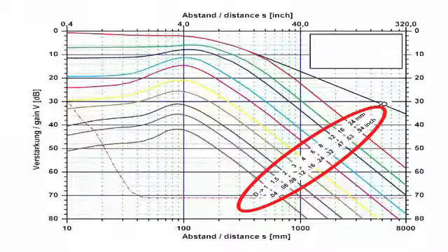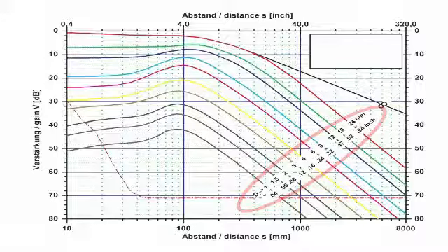In practice, different types of reflectors can be used as reference reflectors. When testing using normal beam and TR probes, a flat back wall is often used, which is struck perpendicularly by the sound wave. This can either be the back wall of the workpiece itself or the back wall of a reference block.